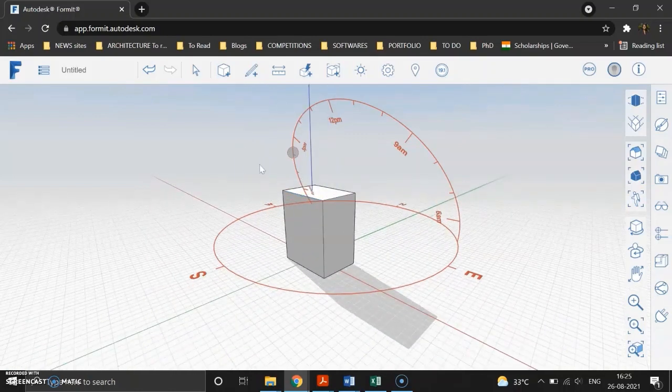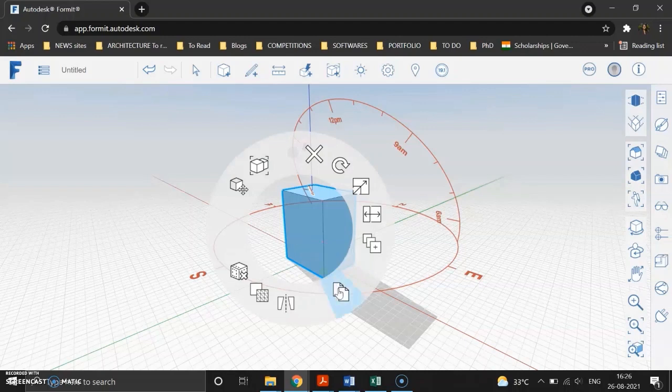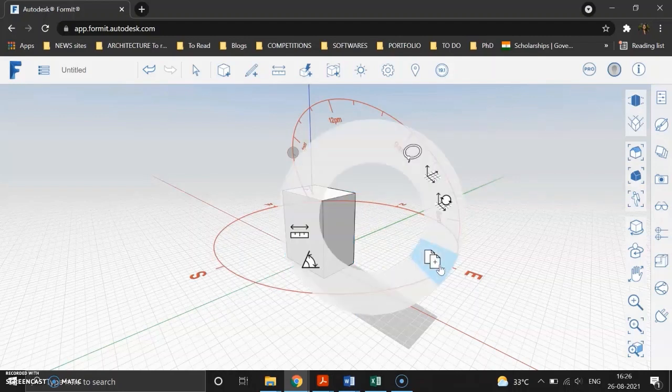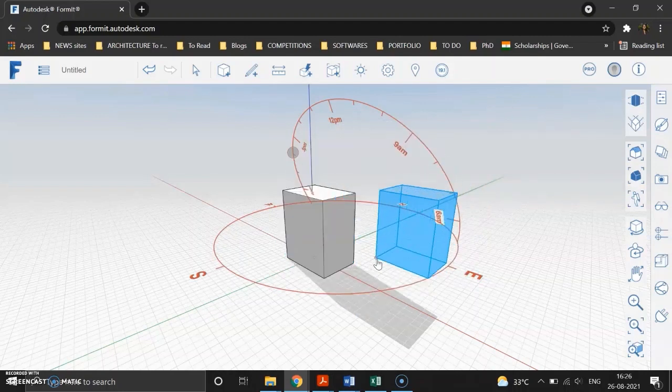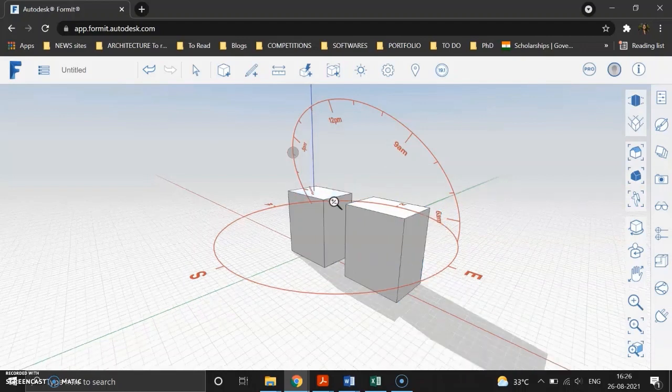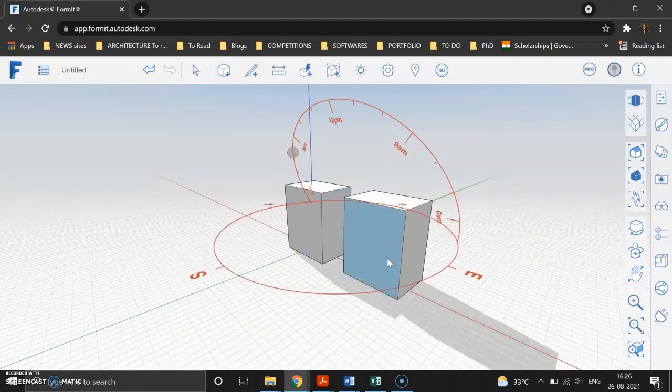So similarly, if you want to look at the impacts of one building's shadow on another building, let's say for example in row houses, you could simply copy this unit by right clicking the mouse button. You will have these different options. For example, I have copy here, and there will be paste here after I copy it. So I've copied this model, I'm right clicking again and I have paste here. So I'm pasting it. Let's say I just want to paste it in the same alignment. Okay, so I have put the next building on the east side of our previous building.